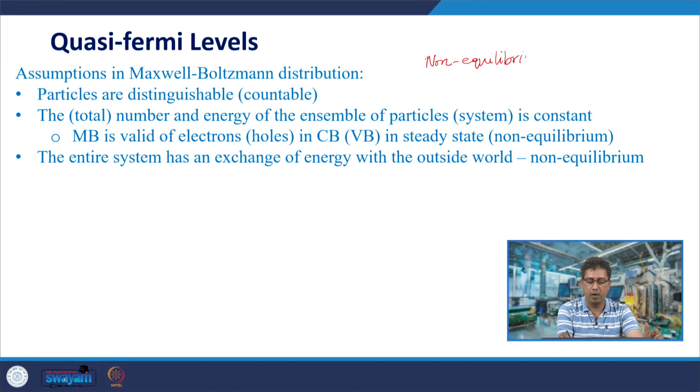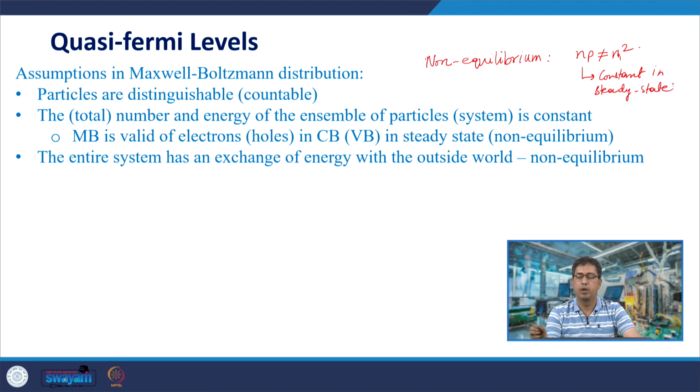So, in non-equilibrium, the law of mass action is not valid. np would be a constant if it is steady state, but it would not be equal to ni squared. Therefore, the Fermi level as we define in equilibrium condition would not be valid.